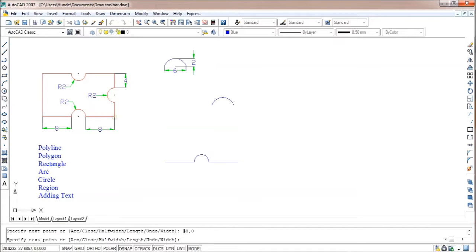Again at this point, the next part is line, which is vertical line having the distance of 4 drawing unit. So I don't need to switch to other command. I have to continue with line command. From this point, this is my reference point now. I have to move 4 distance towards y, 0 distance towards x. So I have to type at 0 towards x, comma 4 towards y. Enter. Now I get this vertical line.